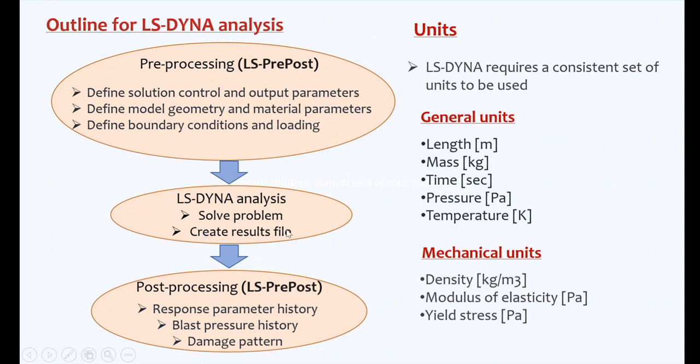Then you have to post-process the results file using LS-PrePost, so that you get the response parameter histories, like stress history and strain history, and you can get the blast pressure history. Also the damage pattern that I have already shown you in the first slide, like how your column is going to be damaged, you can obtain using post-processing.